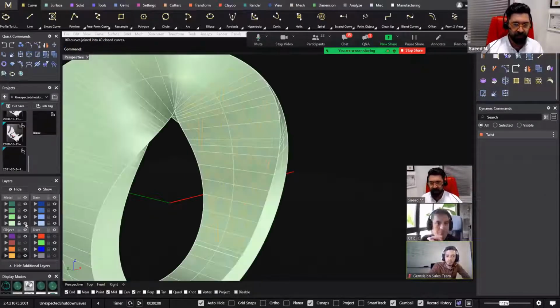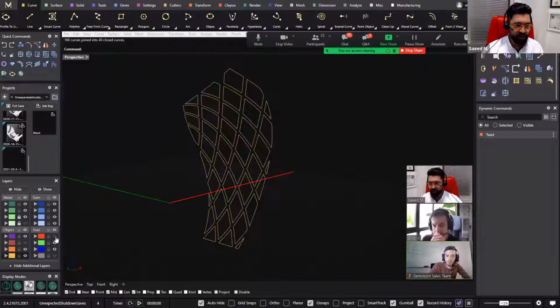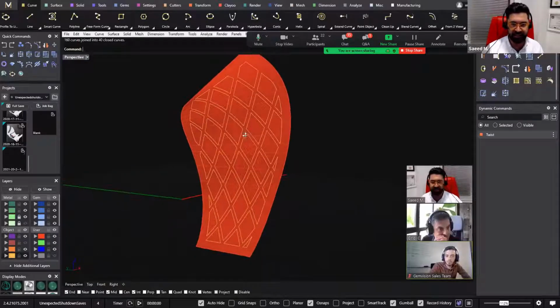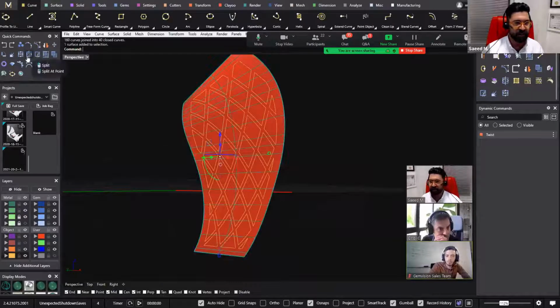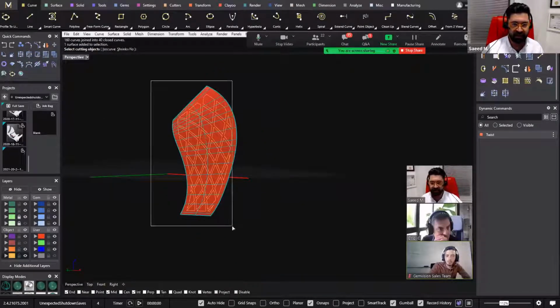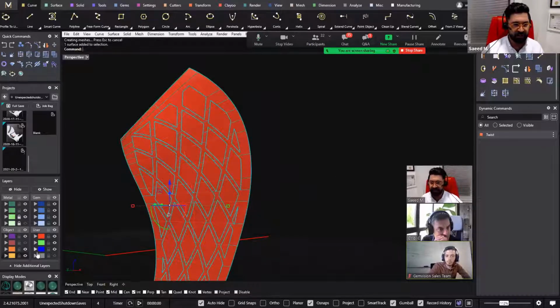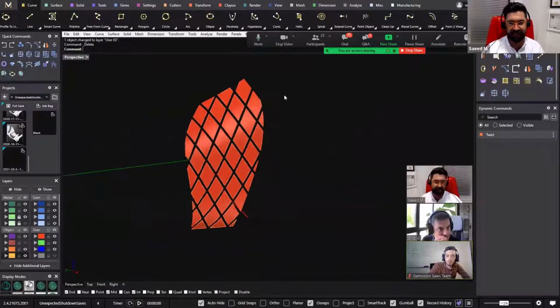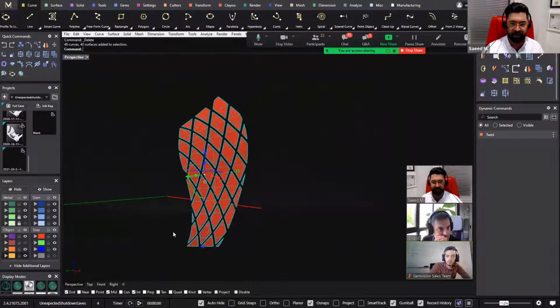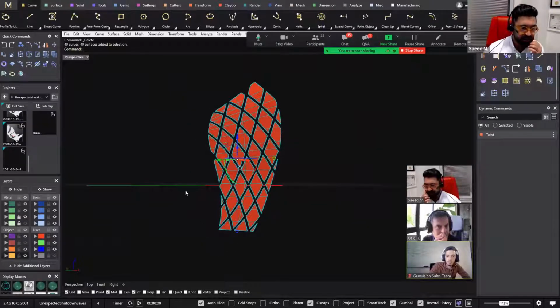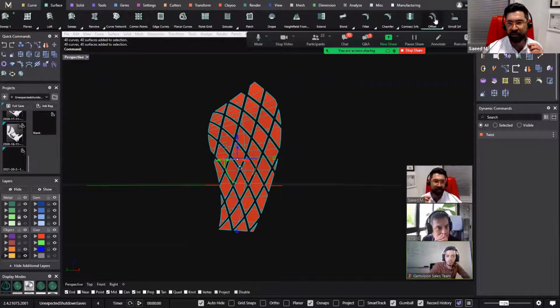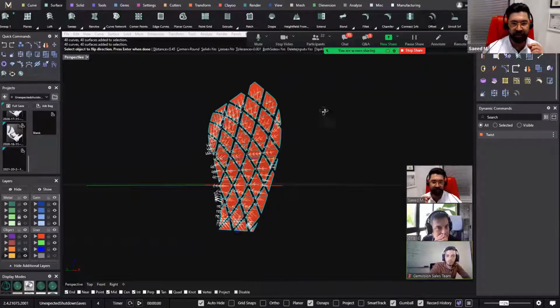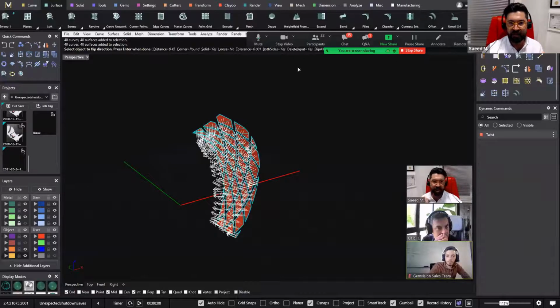Okay. So I'm going to turn on this single surface, click on split, and click all these curves or select them from the layer, and click on this big surface and delete it. And as you can see, we have a very beautiful lozenge pattern here. And I select all the surfaces, go to the surface menu and do the offset surface.